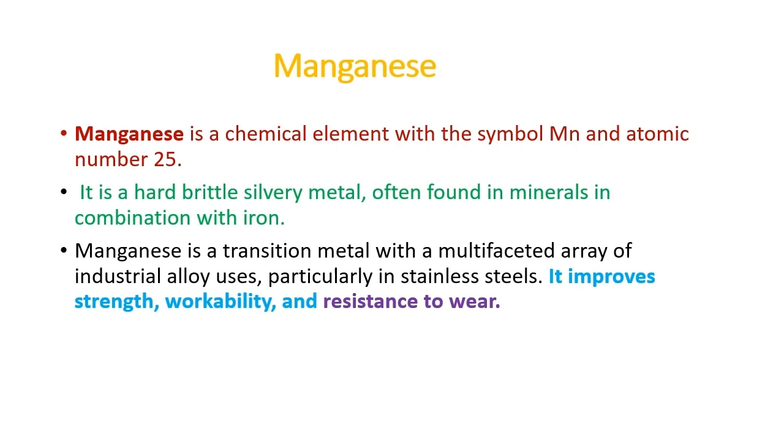So we have learned about iron, carbon, nickel, chromium, molybdenum, and manganese. These are the main 6 materials that are used to make stainless steel or steel, carbon steel, high temperature steel, and low temperature steel. So we now know the properties of these materials, and depending on the various percentages of these materials, the grades vary. So now if any random material is given to us and the chemical composition is also told to us, then we can have an idea about what the mechanical strength will be, and what the resistance to corrosion of that particular material will be.